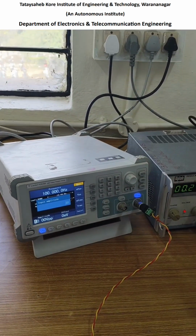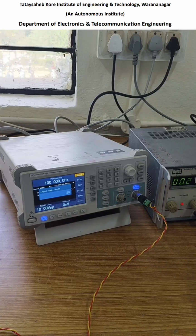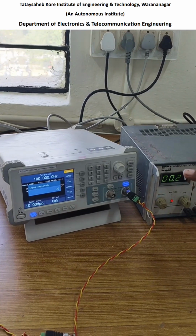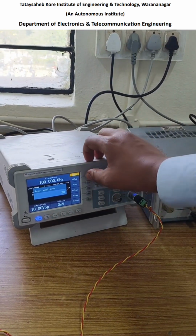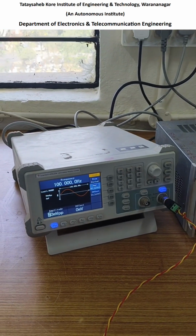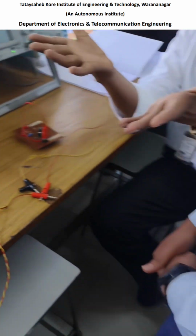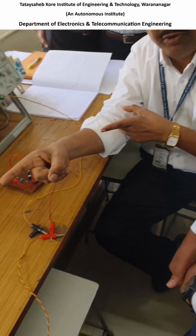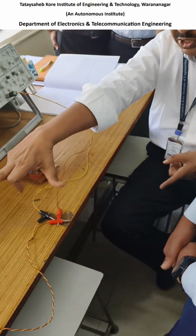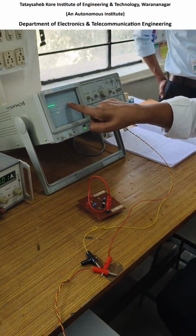Correspondingly, where millivolt peak to peak is written, that switch you have to press, that is F1. Press F1. Now carefully see. The value of the output signal is 20 millivolt, whatever may be the frequency, that is the next part. So I have set the output to 20 millivolt peak to peak.